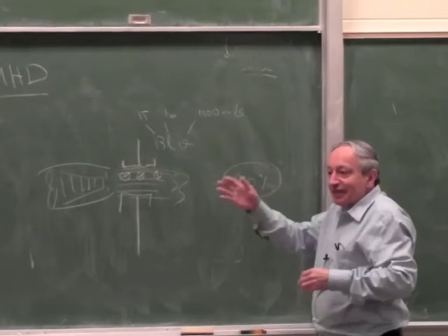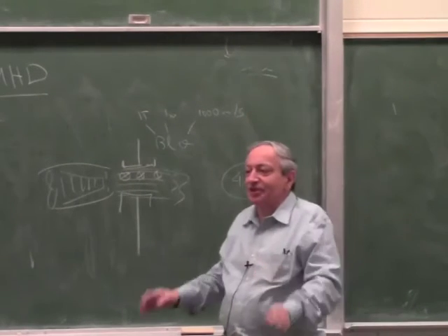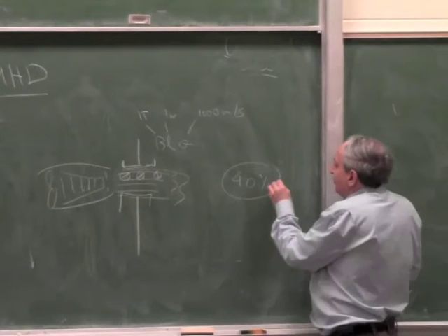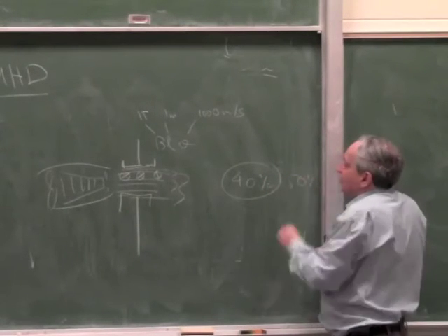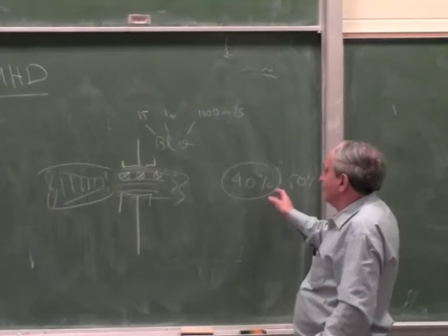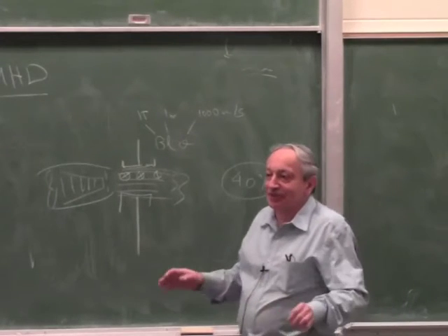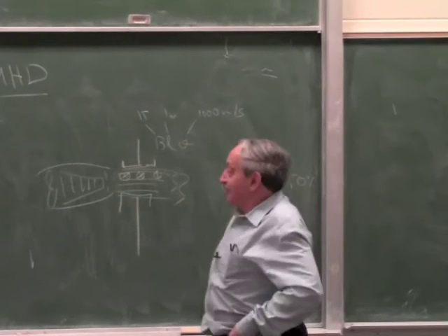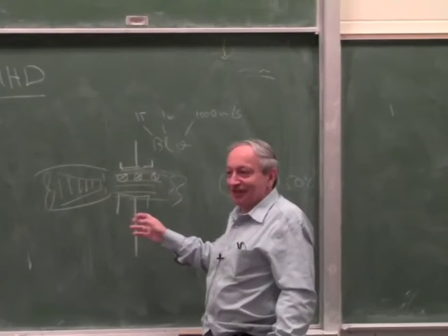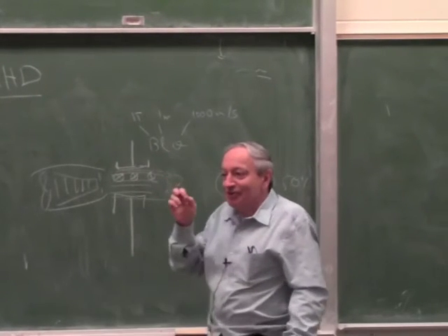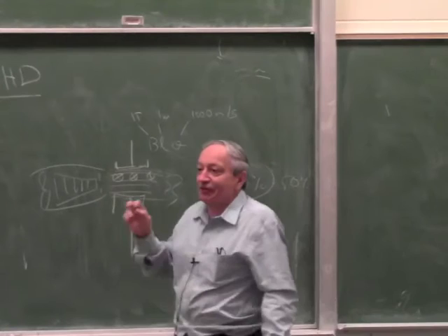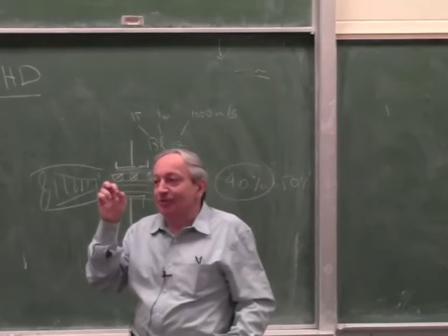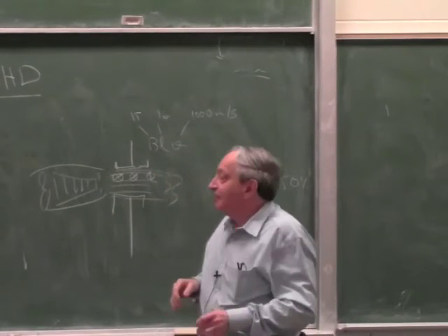You can do multi-cycles and all kinds of things, but a normal steam turbine is 40, maybe 50, 40 to 50. So the gold standard, if it's not 40 to 50% efficient, people lose interest very quickly. But the idea is very fascinating, because again, it can be done at a very small scale. This works at any scale, from a pipette, from microscopic scale to power station scale.